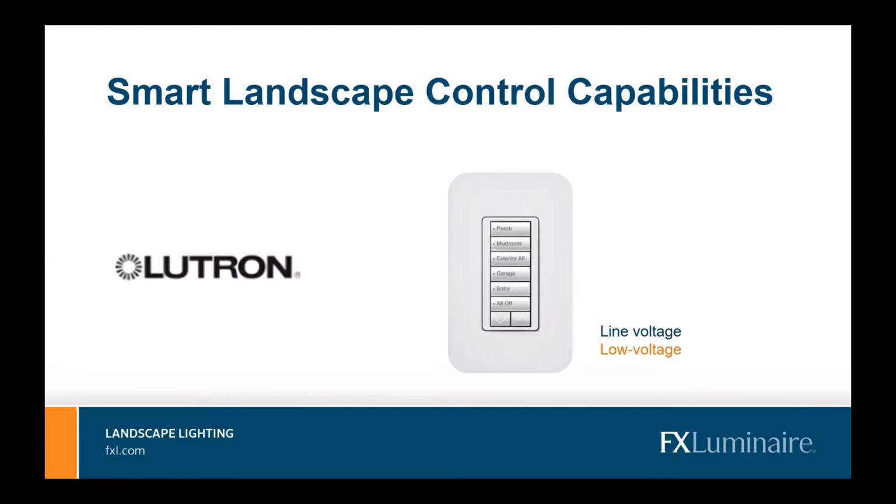When it comes to home automation, typically home automation is controlling indoor line voltage lights or 120 volt lights. They also control outdoor line voltage lights like your porch lights or your garage lights. Being able to integrate with these systems allows you to not only combine line voltage, now you can combine line voltage with low voltage. So for example, in my Lutron system, I can take this keypad and I can program each of these different buttons to not only turn on line voltage lights, but my low voltage lights as well.